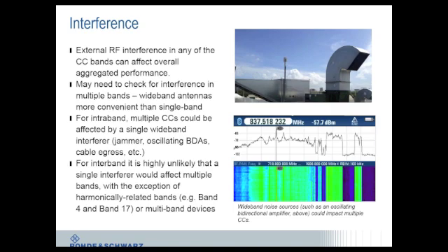One more thing before we move on from this slide. One interference-related question we get a lot is about testing for passive intermodulation, or PIM. As deployments move indoors like DAS systems, microcells, etc., that means we're dealing with lower propagation distances, and that diminishes the likelihood of PIM, so as we go forward, that's not expected to be a common interferer.